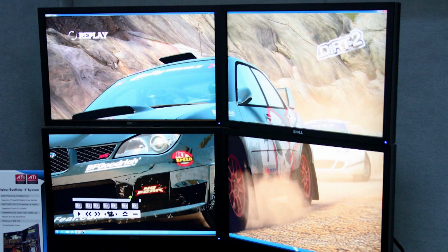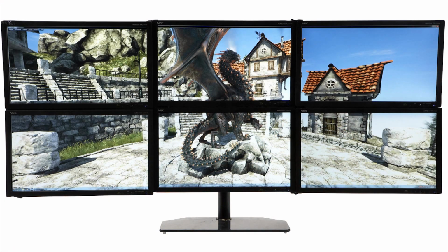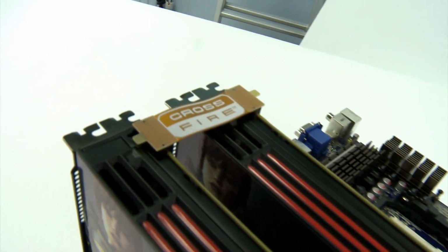The interesting thing about the DisplayPort outputs on this new generation of cards is that they're DisplayPort 1.2 in the hardware. That means that as soon as the drivers become available, we'll actually be able to daisy chain additional monitors to the DisplayPort outputs and give us different monitor configurations. Both of the cards I've shown you also have the connector for hardware Crossfire, so we can put a second card into the system and accelerate the performance just as before with Crossfire X.